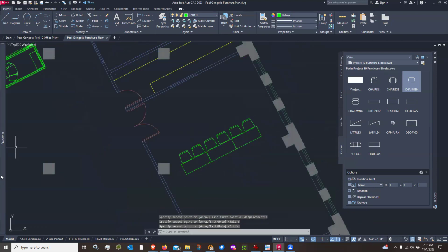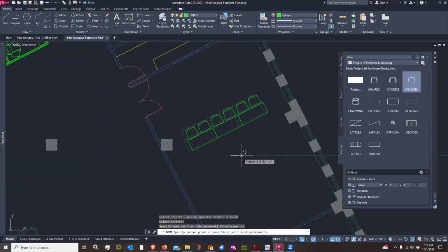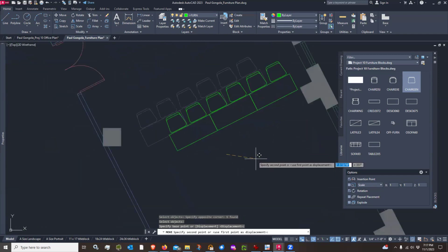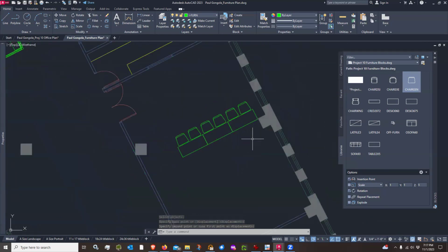And I think what I'm going to do is start with the one that's near this corner over here. So I've got it close to, but not on that corner. I'm just eyeballing it. And then the spacing for these is 5 feet on center. So I'll have a row back here 5 feet, and then another 5 feet, and then I've got 5 feet this way and 5 feet that way.